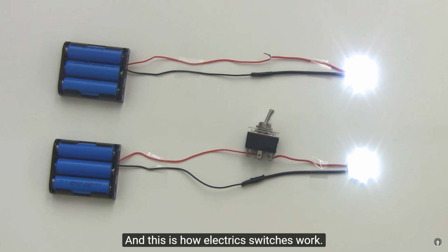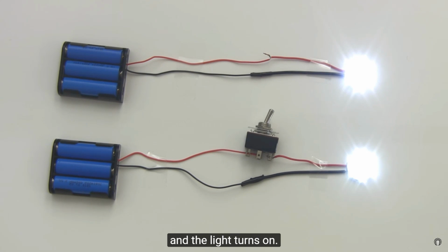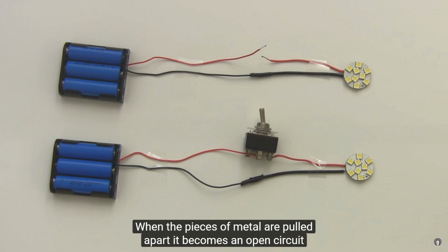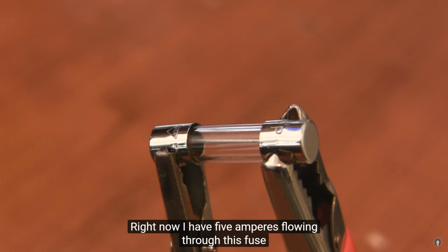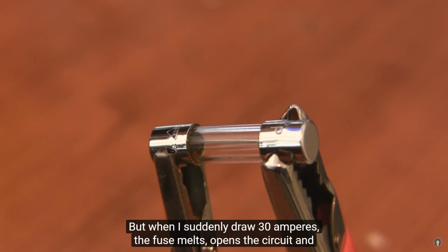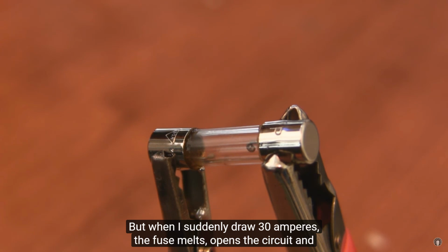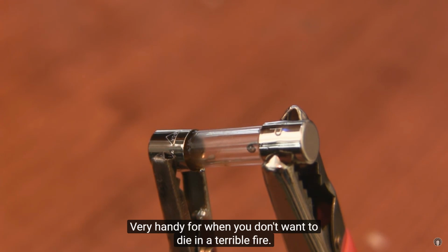And this is how electric switches work. The switch has 2 pieces of metal inside it, and when the pieces of metal touch, you get a complete circuit and the light turns on. When the pieces of metal are pulled apart, it becomes an open circuit and the light turns off. And this is also how fuses work. Right now I have 5 amps flowing through this fuse, which is rated for 15 amps. But when I suddenly draw 30 amps, the fuse melts, opens the circuit, and prevents any current from flowing until the fuse is replaced. Very handy for when you don't want to die in a terrible fire.